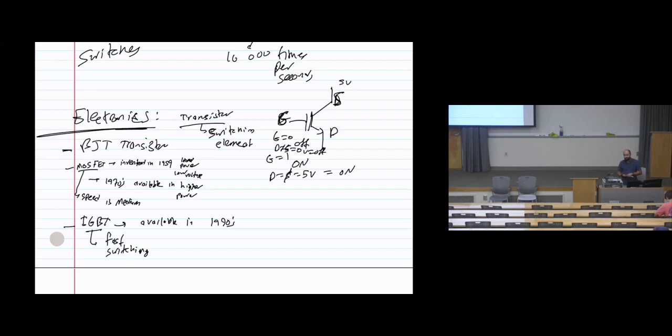There is also one challenge of electric vehicles. When you are running at low speed and you hit the brake, you cannot store this energy into the battery. You need to hit the regular brake, or actually the system will do this, not you. Because if it is going to work as a generator or motor at low speed, there will be a lot of problems. So they are still trying to figure it out.